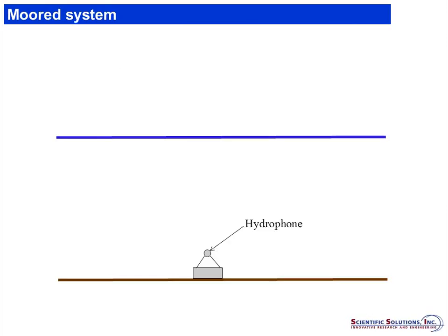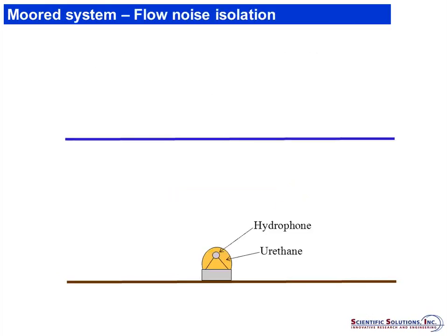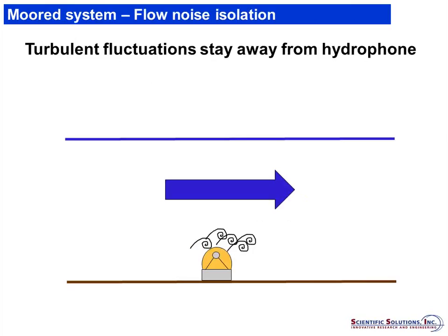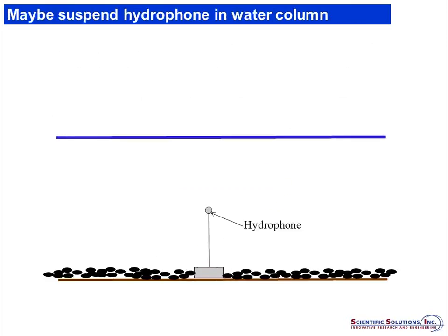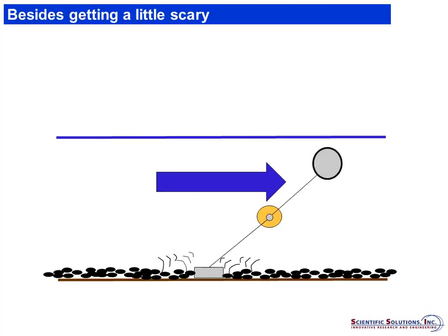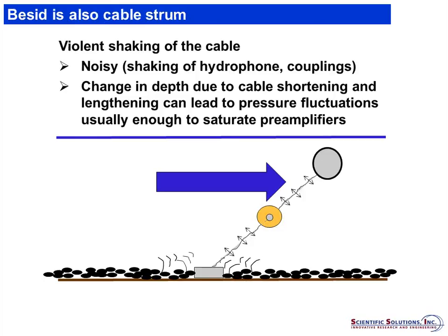Let me just sort of skip ahead. Just click a few times, and I'll just talk for a little bit as we go through the time. There are all sorts of problems with flow noise over hydrophones, and what we found is that the best way to make these measurements, because of the various issues with how you can deploy things, is to deploy a hydrophone off of a drifting buoy and then let it drift with the current and make the measurements. And we were successfully able to do that with the ORPC tidal turbine.